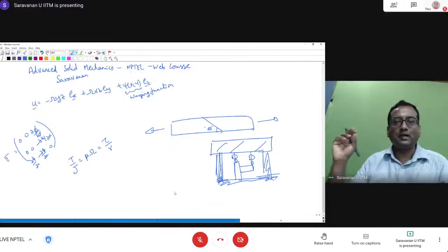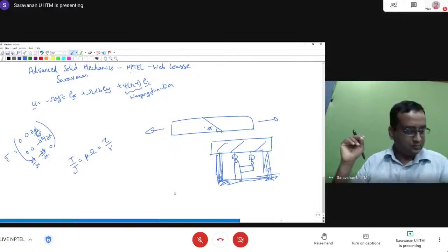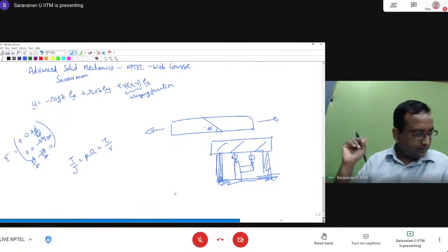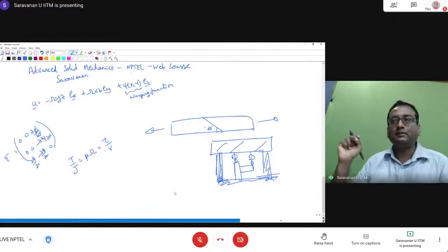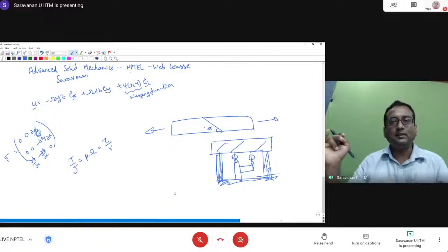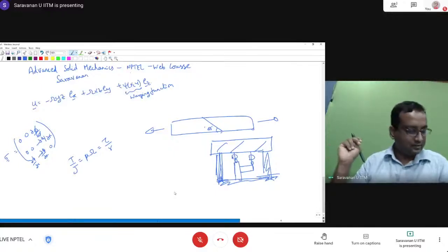Extremum normal stresses, maximum as well as minimum. The second one is an in-between value, which is not of much use. The three principal stresses represent the maximum normal stress and the minimum normal stress for a given stress tensor. The principal directions represent the direction on which the maximum normal stress and the minimum normal stress act.